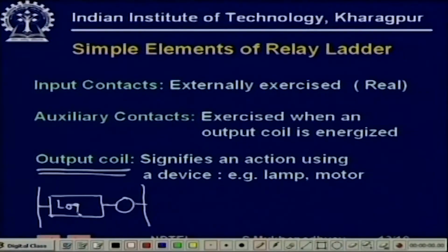So, this is logic. Now, today we will study where the logics are just made of some input and output contacts. In fact, they can be made of many things. Actually these input and output contacts are, for those who have studied digital electronics, like combinational circuits, while we could also put other elements within this logic, to make this logic a sequential logic using timers and counters and things like that. So, that we will see in the next lesson. Today we are going to see circuits which are made simply of various kinds of switches. So, basically combinational logic.